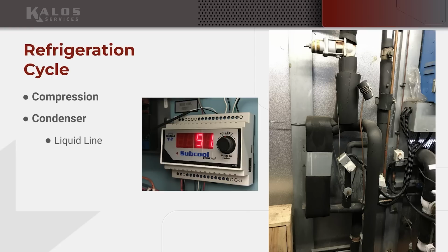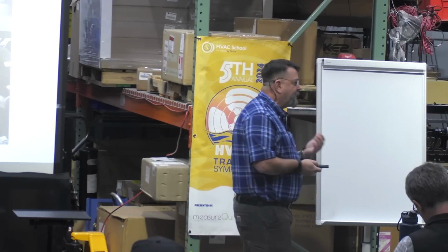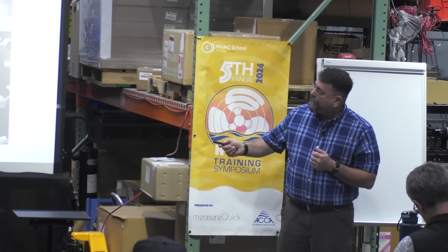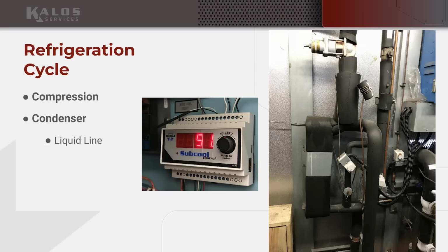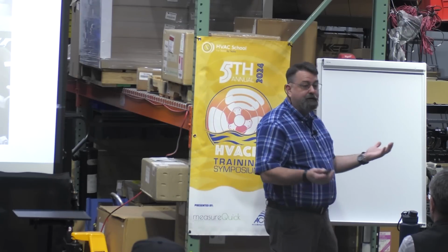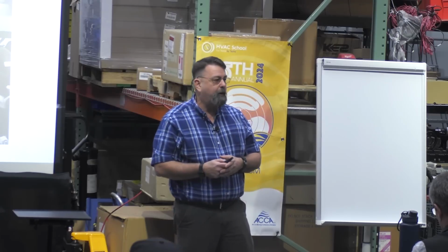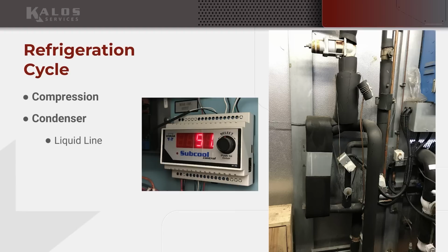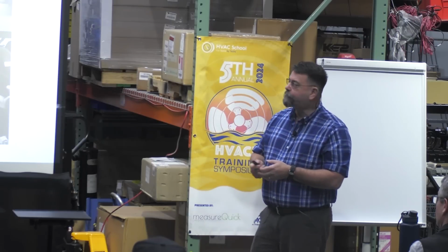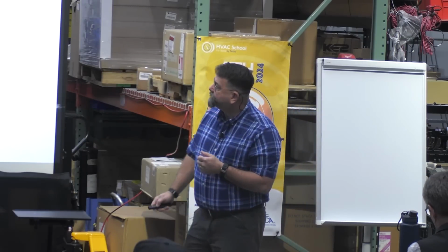I threw this guy over here just to point out that anytime we're looking at mechanical valves, there's another one up there. Anytime we see those mechanical valves, that's the majority of what we have out in the world today, and they are slowly going away, right? We're replacing with electronics, okay? Electronic valve and a valve driver, right? Super common to see that. This particular one that I'm showing you is a retrofit on a 20-year-old rack, and we've added electronic valves. Why not, right? It just makes it more efficient. Doesn't really matter how old it is.